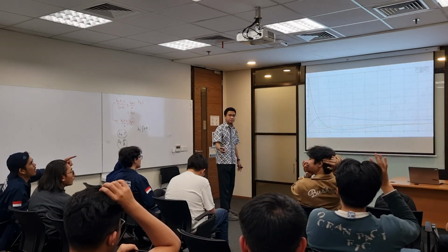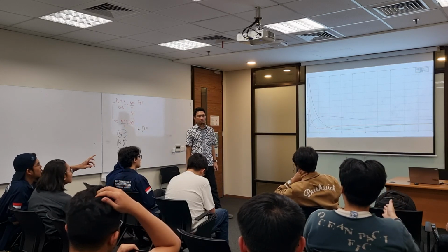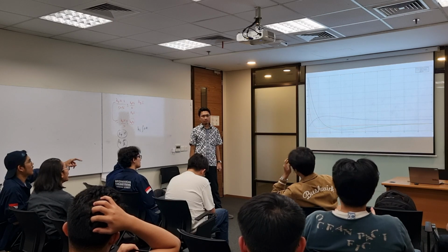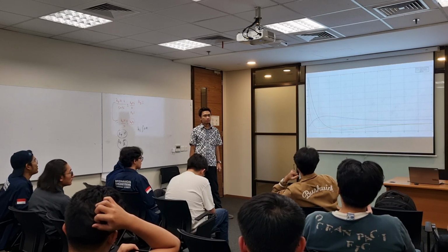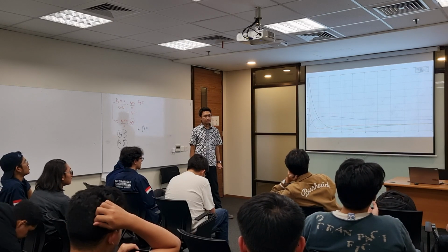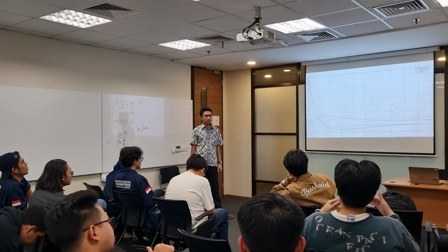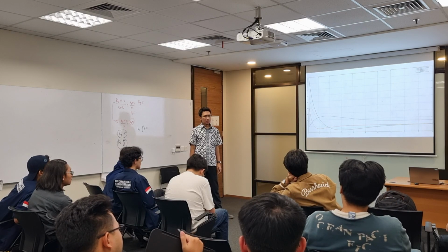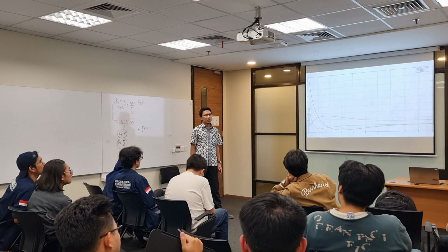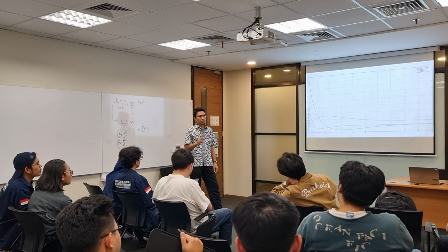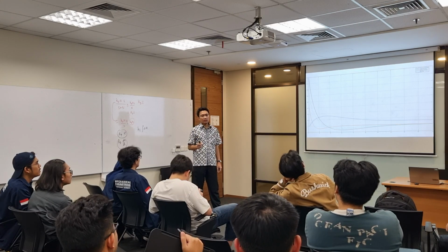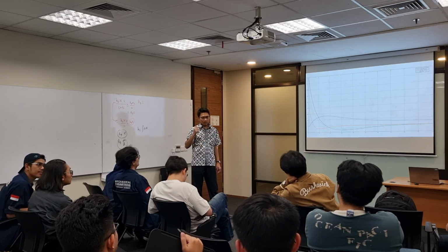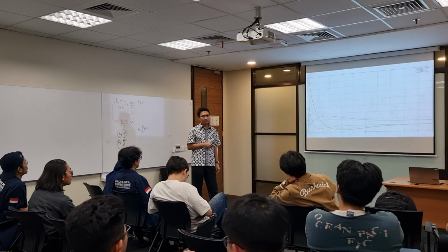The derivative doesn't take the disturbance into account. When you only apply proportional and derivative control, it cannot handle the disturbance. The one that cancels out the disturbance is the integral control.